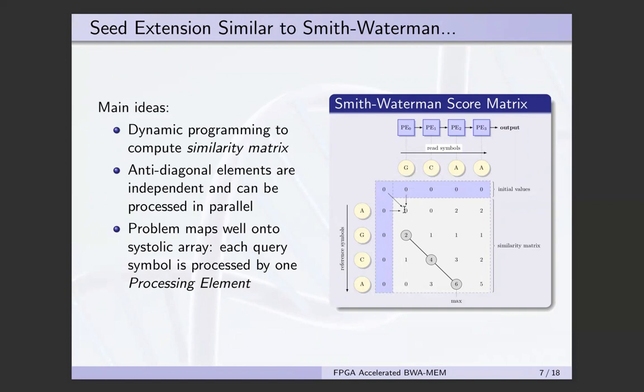At the end, after the whole matrix is filled out, we trace back the highest scoring path between the 2 different sequences to identify the actual alignment between these two sequences. This matrix can be calculated on FPGAs using a systolic array. The systolic array usually contains multiple processing elements, and each of them calculates an individual computation, computing an individual entry in the scoring matrix.